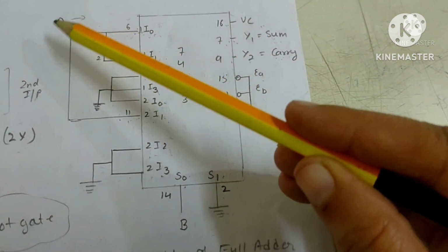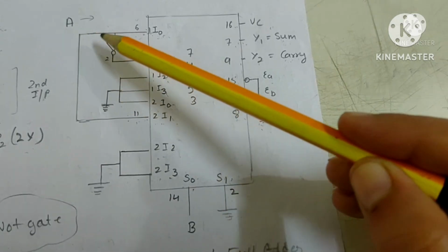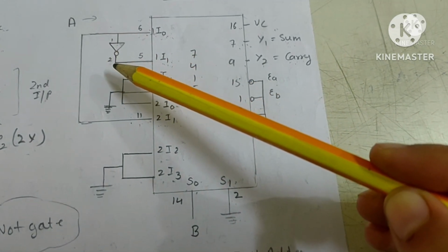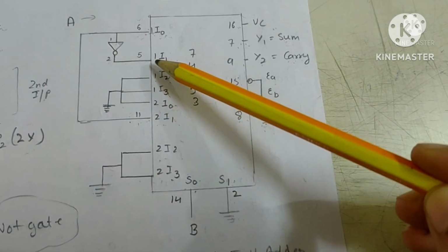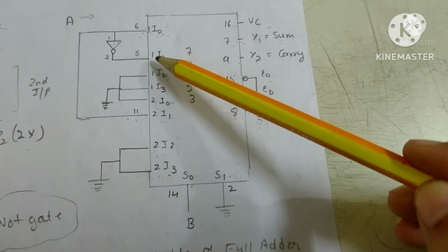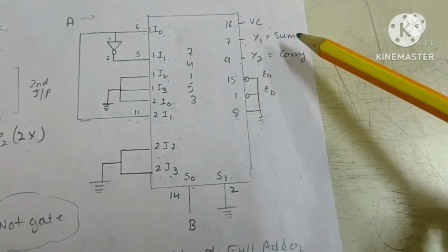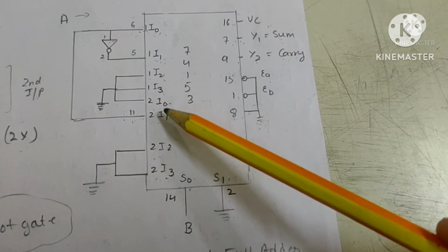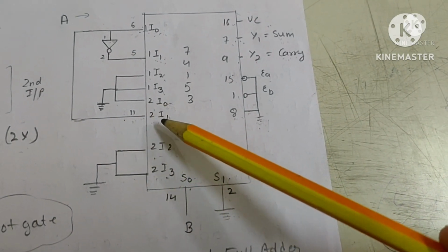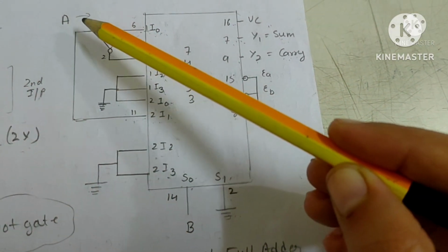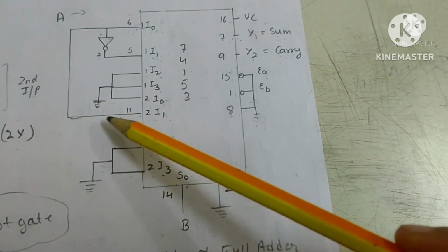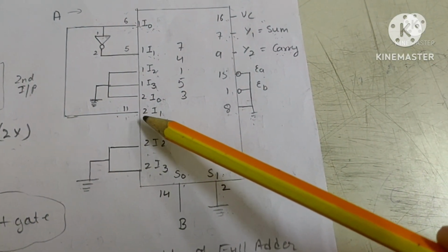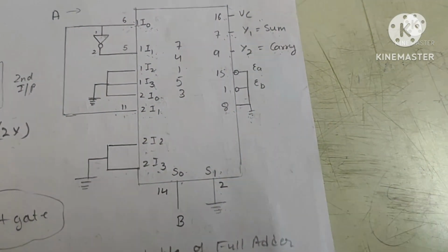Okay. Next we are given the logic 1. If I give the logic 1 through the NOT gate, it will become 0. Okay. That means the sum part will be 0 now. And here for the carry part, we are focusing on this part. Okay. For the carry part, the logic 1 is coming as a feedback from here, right? And this carry part will be 1 here.